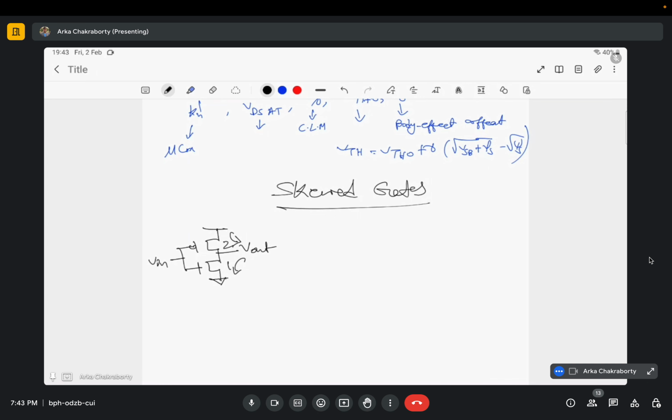So this is basically a circuit with the same rise time and the same fall time. But I can make it a low skewed circuit. Instead of 2, I will use lesser values, say 1 or 0.5 if it is allowed. Not all the time is 0.5 allowed, but in some technologies it is.